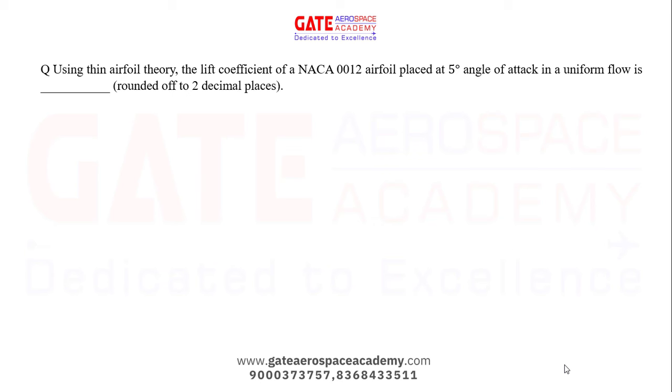CL is equal to the slope A into the angle of attack alpha. So alpha is equal to 5 degree. CL, lift coefficient, is equal to A into alpha. A is 2 pi, alpha is 5 degree into pi by 180, which is equal to pi square by 18. That is equal to 0.55.